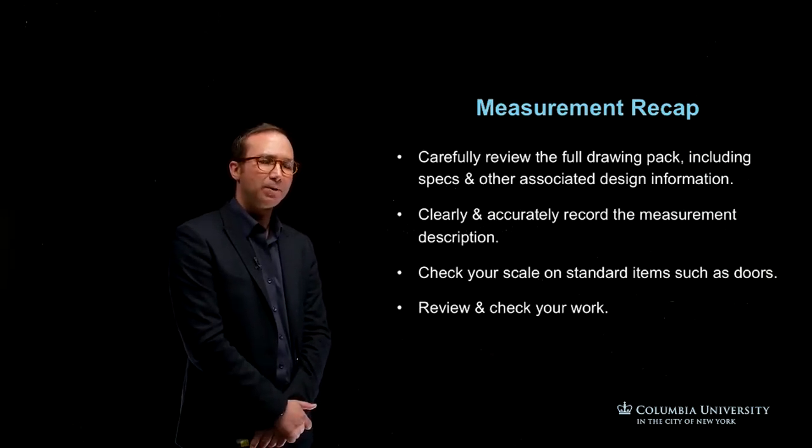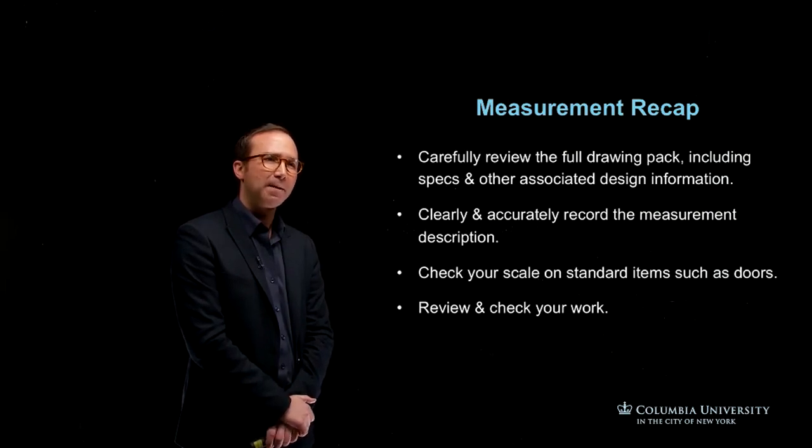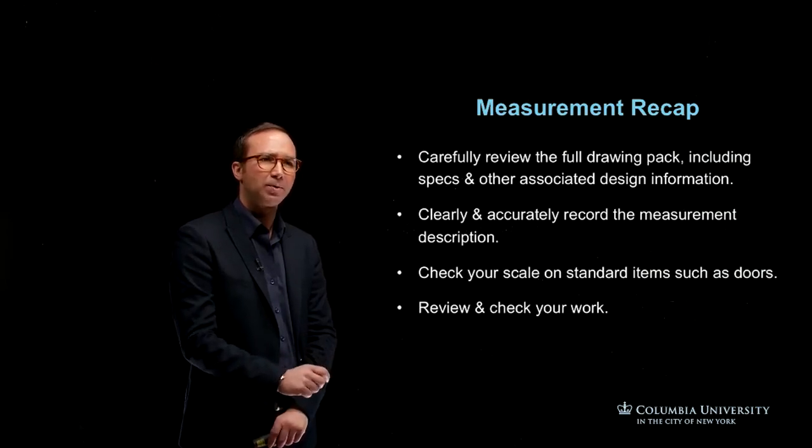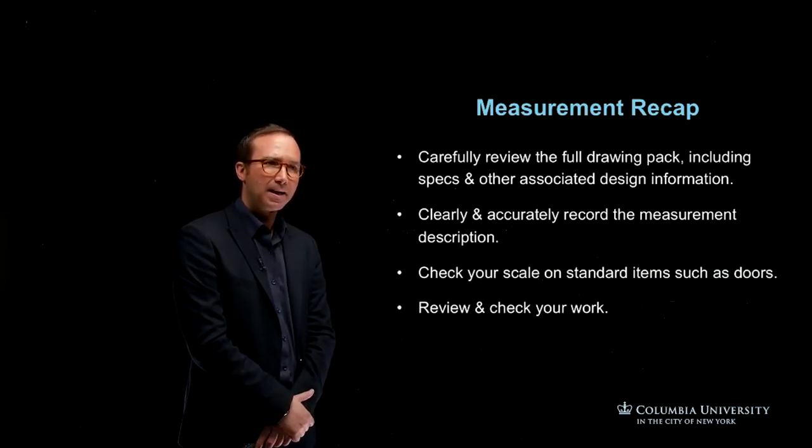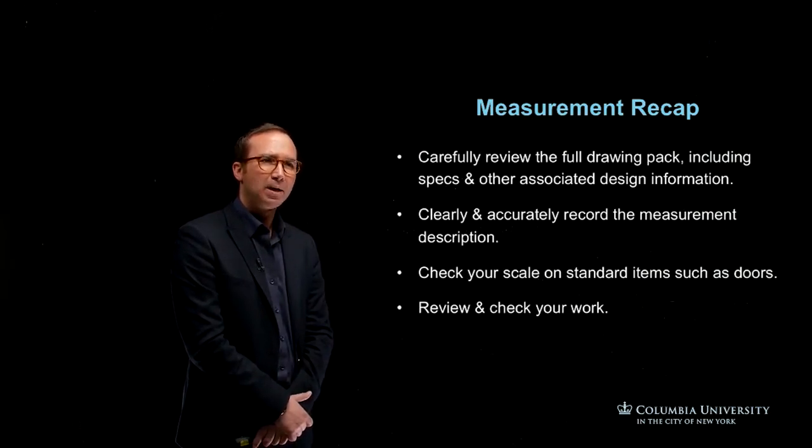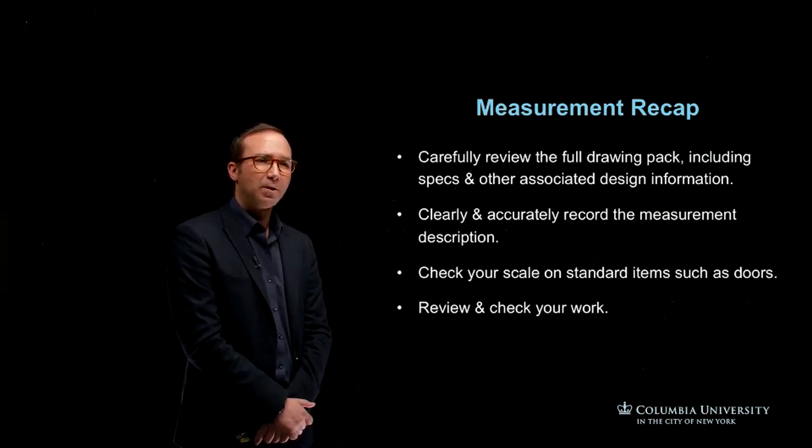It's really important that you go through the drawing pack. Now sometimes you might see a drawing that you think is not relevant to the actual measurement you're doing. But I'll tell you now, every single drawing in that pack is really important and it's there for a reason. You get a lot more information by looking at all the other areas as well, such as the structural steelwork, design pack, and all the other engineering packs. It really does paint a full picture. So the examples I just gave you there were architectural items, and really, by looking at the structural items as well, you're going to be gaining a lot more information on the measurement itself.